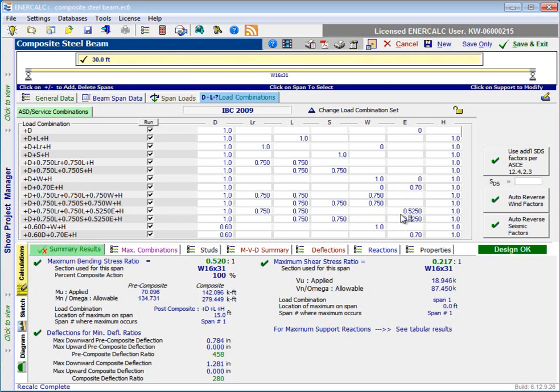Changing values of load combination factors within a calculation like this one does not go back and change the factor in the original database. It only makes a one-time change to the factor right here in this calculation. So you can feel comfortable making any changes that are calculation specific, and they will be retained for the remainder of this calculation, but they won't affect any other calcs based on this template, either prior calculations nor those that will follow based on this template.